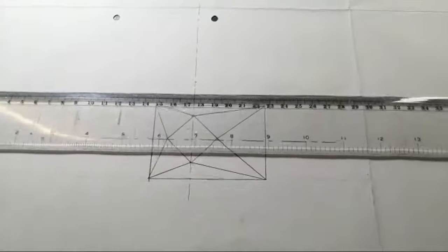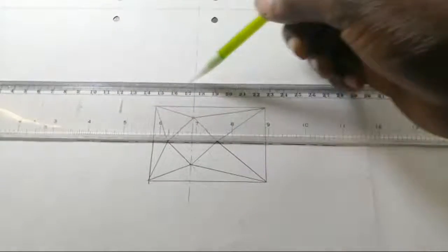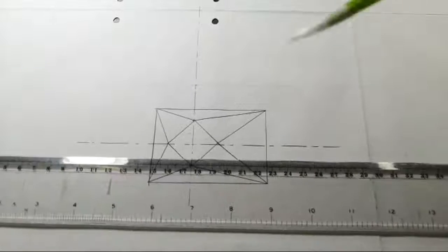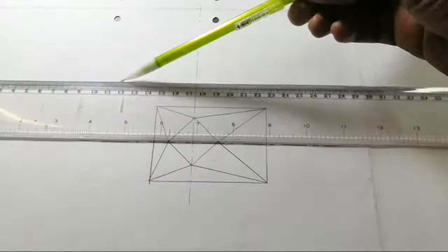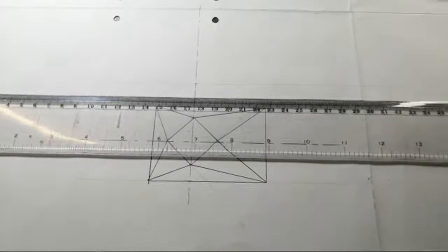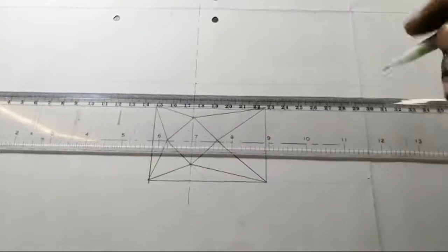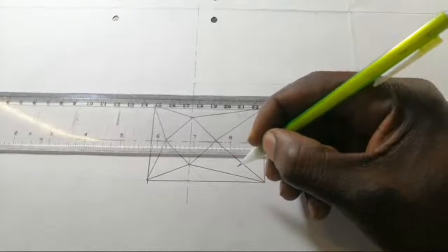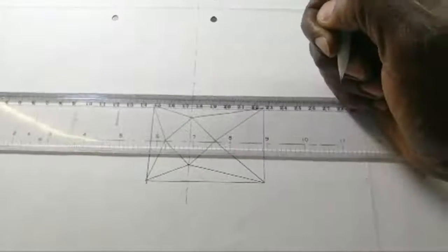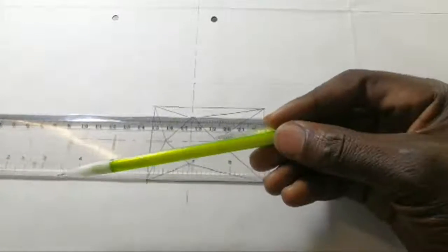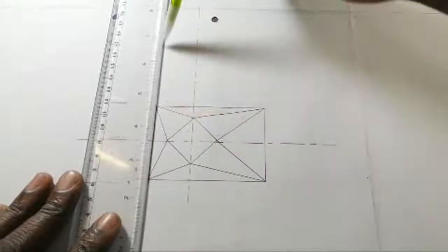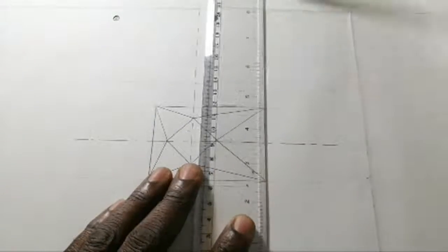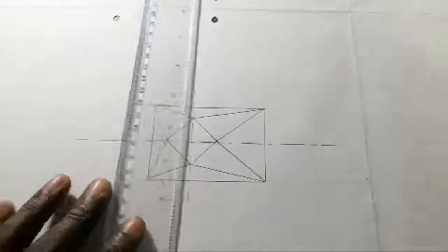So now from there, I draw a horizontal faint line. Remember, how do you draw a faint line? You hold your pencil at the end like this, and you pull your pencil when you're drawing. You don't push. But when you want a solid line or a dark line, that's how you hold your pencil, and you even push it when you're drawing. When you're drawing faint, you hold it here, then you pull. Now construct it up faint, and here faint, and here faint, and here faint.